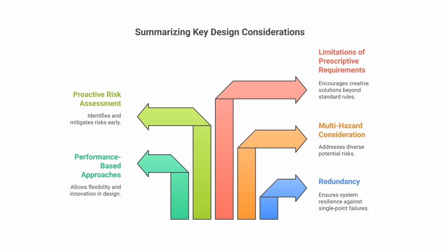Of course, we have to have redundancy, where my system should have enough multiple failure paths that prove it to be resilient against single point failure. So we cannot have a single point failure. Always we need to have different loading paths where the effect of the applied extreme loading can be dissipated.